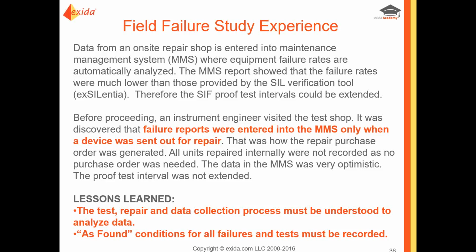Okay, got another question. Do the pressure sensor failure rates include failures due to issues about impulse lines being plugged? Good question. But the answer in this case, that particular analysis did not include manifold valve and impulse lines. It did include, in fact, we have the data with or without a remote seal. Impulse lines were considered separately. And of course, one of the reasons it's really important that you know that is when you compare data, you must understand if the impulse lines are included in the comparison or not.